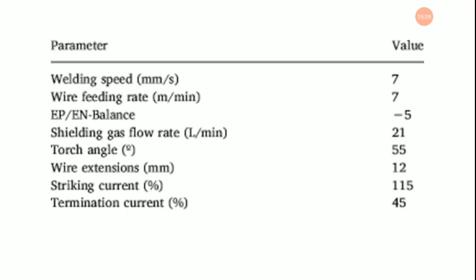Now a higher welding speed lessens the time for contact between the arc and base material with submerged filler material, and this leads to lower back width. The decrease in welding speed increases the back width. This is because there is more time for contact between the arc and the face of the base metal with submerged filler material. So as the frequency increases, back width goes on decreasing. This is because of more pulse rate and more heat contact in the narrow direction.